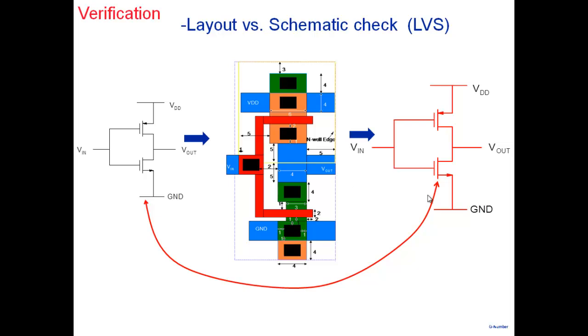And again, as we have been saying, because one is not doing a layout of an inverter or an AND gate, one is doing layout of hundreds of thousands of gates. So all these steps, there is a CAD tool which will do this for you, which will extract a new schematic and compare it with the old schematic and tell you whether the LVS has passed the test or not. That's an important step in the design process where you compare the two schematics.